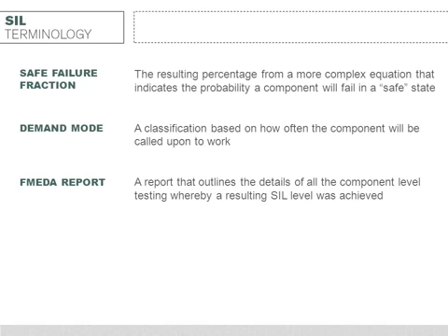Now, a lot of analysis and computations go into determining things like probability of failure on demand and safe failure fraction. You probably don't need to know all of this kind of thing for everyday sales, but I've put a couple other things here also that you might get asked about along the way. One of those is demand mode. That's something you may have noticed on the last slide in relation to PFD.